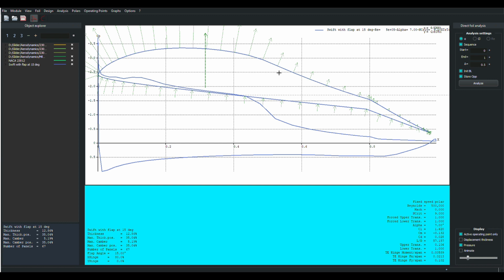And it's amazing the things that you trip over. I don't think anybody's ever looked at this closely before, but now we have a clue, and I can go back to the 23012 and look at where that pressure reversal occurs near the trailing edge, do the little bit of reflex that's in there, and I can create a trailing edge flap that might be pretty close to optimum.